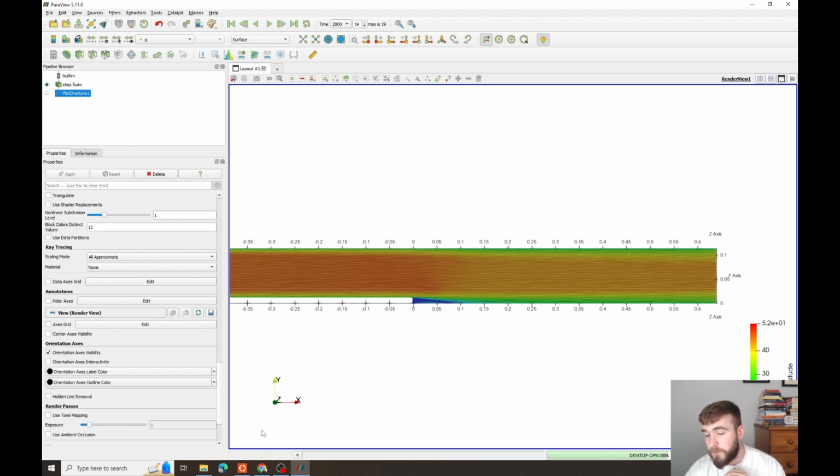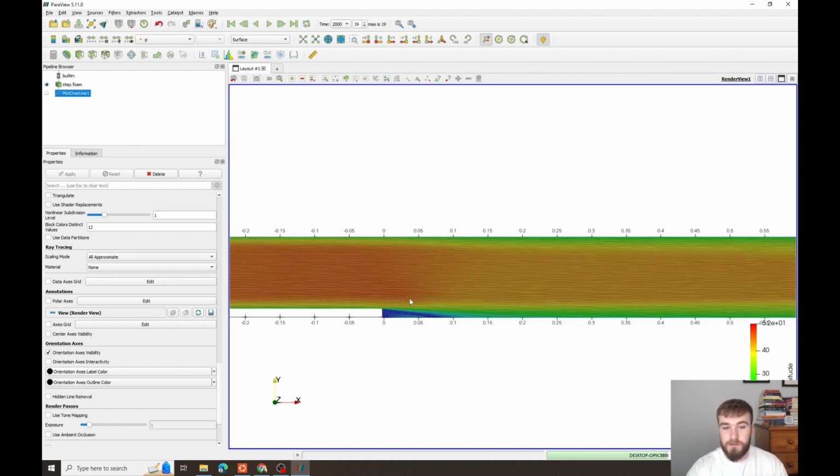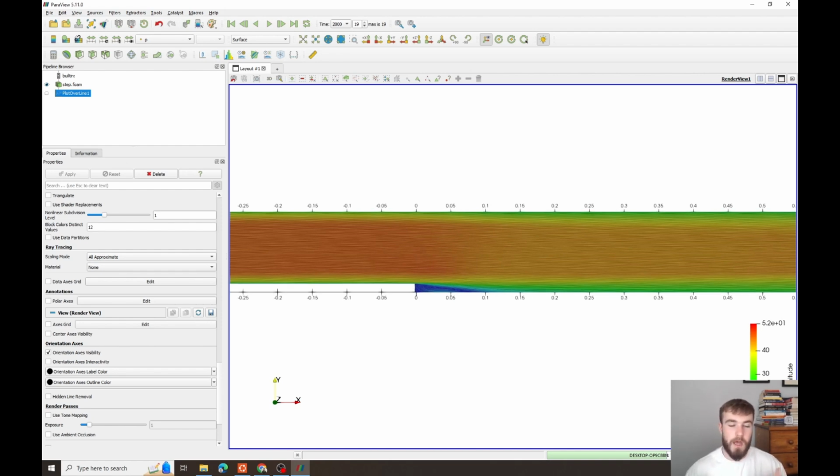and that's pretty much our first simulation in OpenFOAM. And in the next few videos, I'm going to be showing you how to do your own simulation setup. So, for example, if I create a mesh, how can I then import that into OpenFOAM and run a simulation? I'm going to do a lot of my meshing in external software like ANSYS Fluent, because you can do that for free. If you have the student version, you can just mesh your domain in either SpaceClaim or in Design Modeler, and then you can bring it into OpenFOAM and then define the boundaries and move on. So in the next few videos, I'm going to be showing you how to run your own test case in OpenFOAM for a random geometry that you've maybe created yourself and maybe your own mesh.